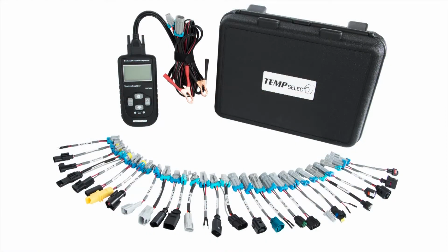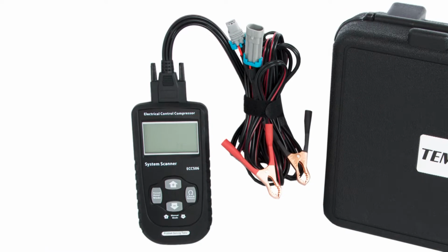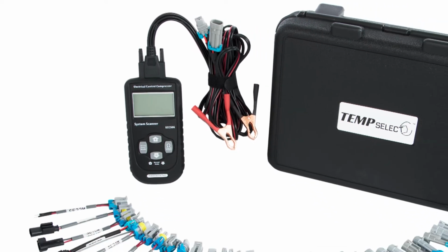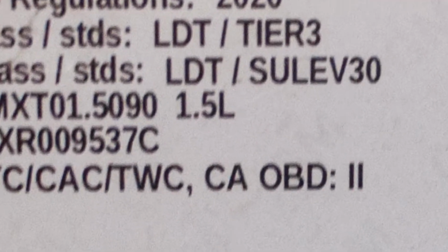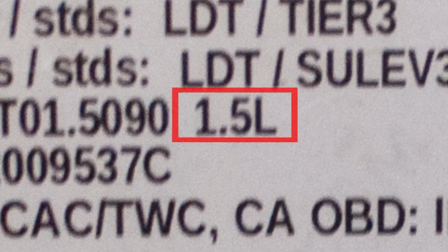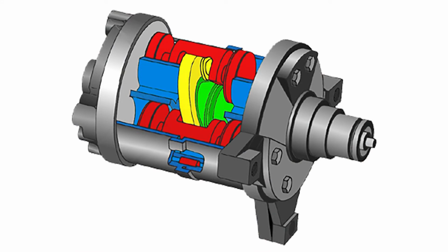But to really understand the power and value of this tool, we need to understand how a variable displacement compressor actually works and the difficulties associated with successfully diagnosing them. Modern, smaller capacity engines are especially sensitive to transient loads, such as compressor cycling. Early compressors were fixed displacement designs.